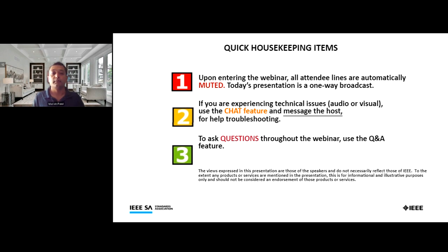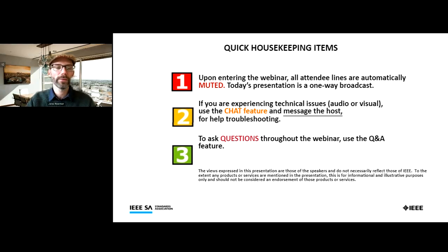Yeah, thank you, Manish. And thank you, whoever asked that question. Certainly there's a lot of interest around IEEE 2800 harmonic current and voltage limit requirements. So you may remember that 2800 does not specify harmonic voltage limits. It recommends to the transmission planner to specify those. Now, how can they specify them? It would certainly require some more sophisticated modeling, including a representation of the inverter-based resource in the frequency domain, and to a certain extent, maybe the time domain.